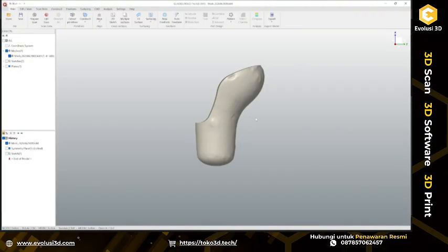So one, if they would recreate a complete shape from, for example, side view, top view, and front view, trim it, and then blend edges, and probably trim away this top part here. Or another way, which is quite more complicated, where guys are using a lot of 3D curves, then loft all that together with guide curves and everything.